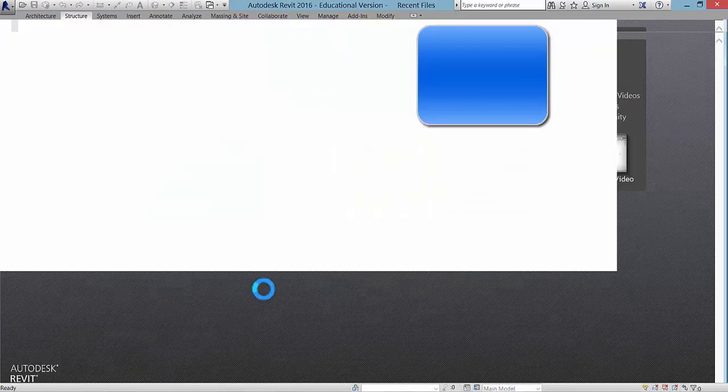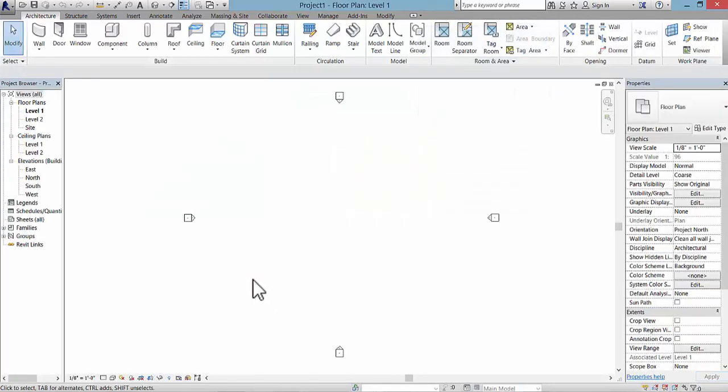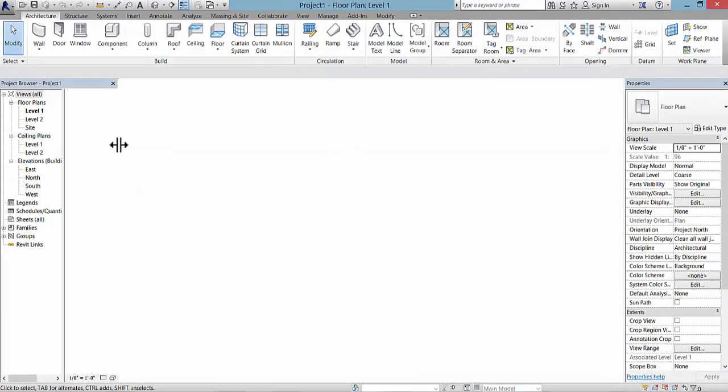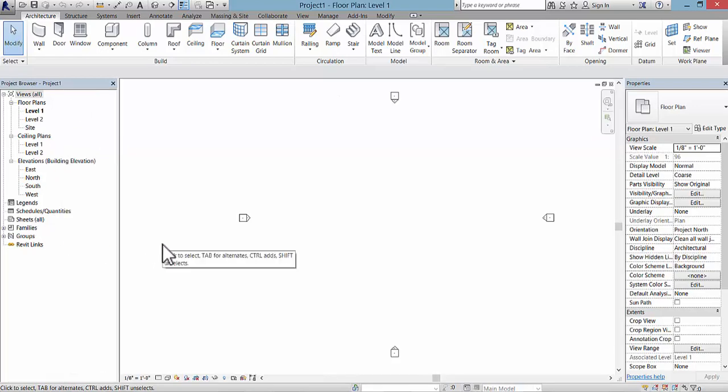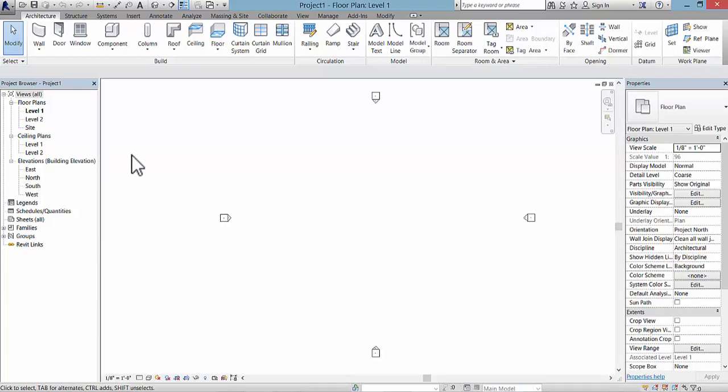It gives us a cleaner slate with only a few levels to work with, but at least you do have some choices. And if you watch the videos about the mechanical systems, you'll see that you can bring in those settings so that one of your views takes on those mechanical settings. So here, let's start on level 1 by creating a grid.